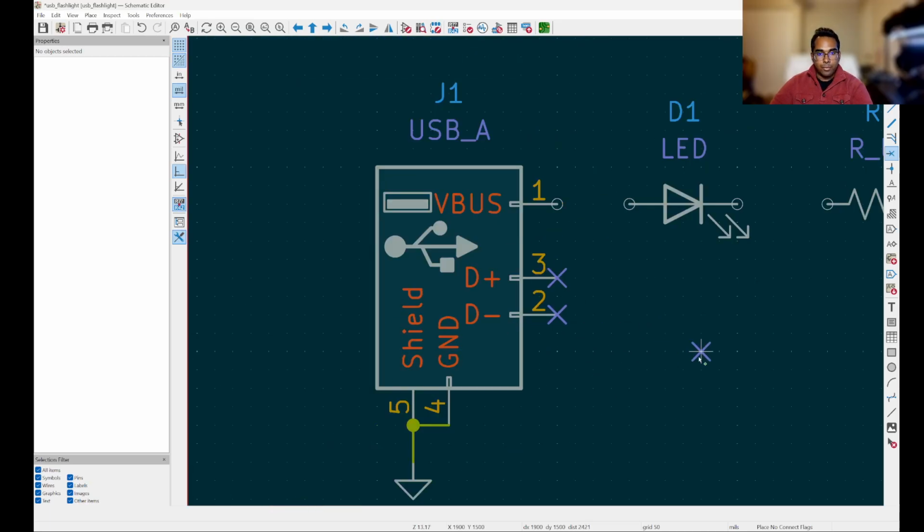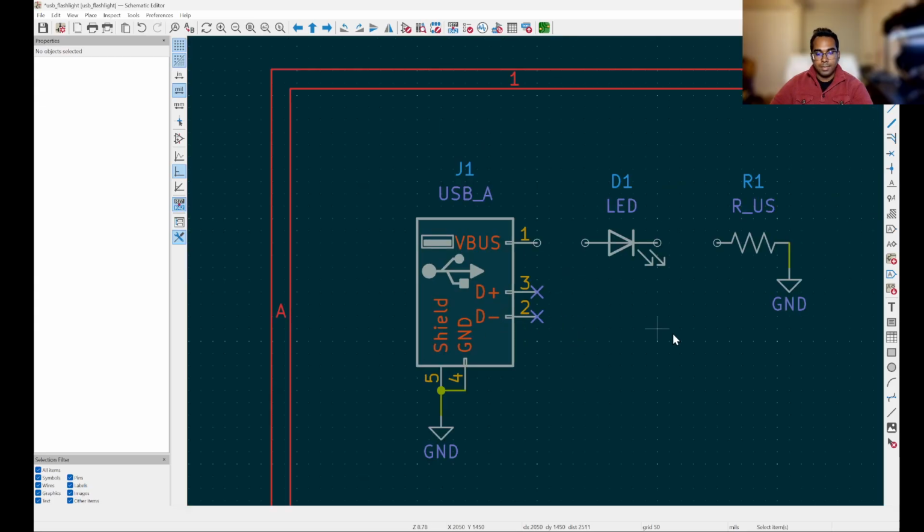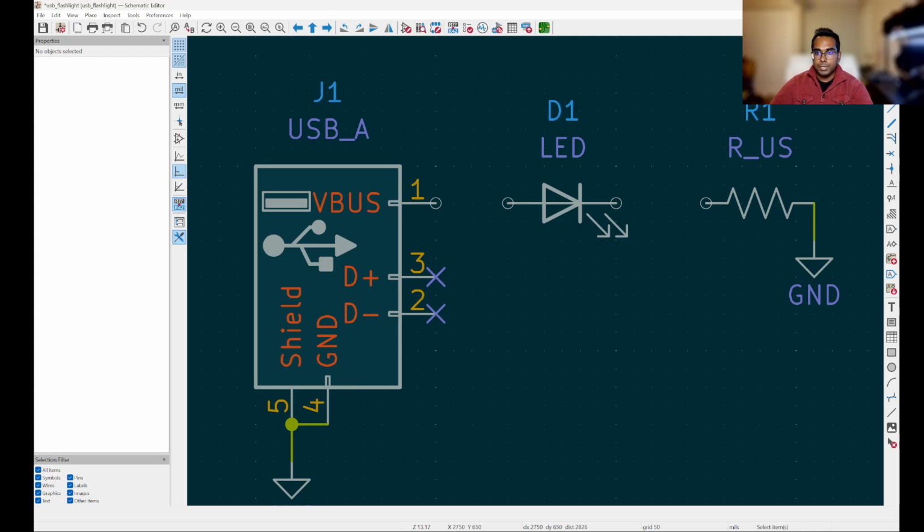So now that we're done placing our no connects, we want to get out of this tool so that we aren't placing any more X's accidentally. To exit out of any of the tools in KiCad, just press Escape, your ESC button on your keyboard. And that will send us back to our regular cursor. You can also always just click on your Select Items button up in the top right to exit out of any one of these options down here. We'll talk about some more of those options later on, but most of them we won't have to use in this case.